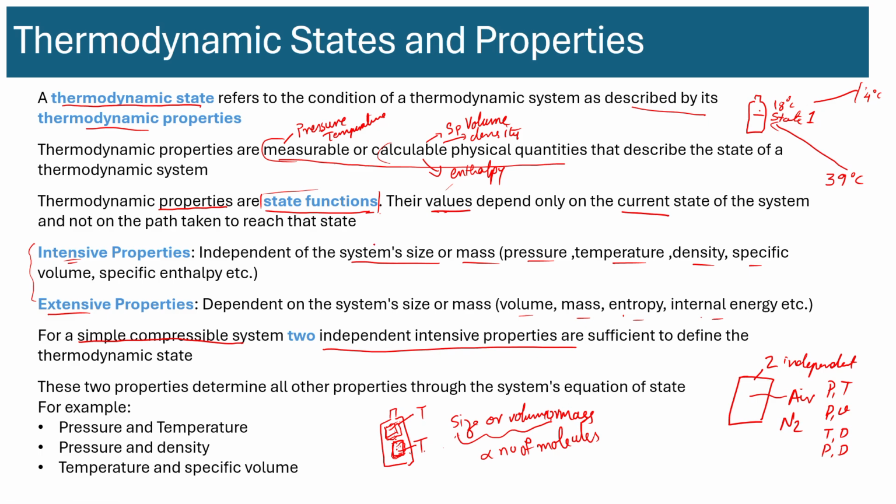The thing that you have to be careful though is they have to be independent. Now, if instead of air you had a mixture of liquid and vapor, for example, of water, in this case, you have to be careful. You can use pressure, volume, temperature, density, pressure, density, all of those are okay, but you cannot use pressure and temperature.